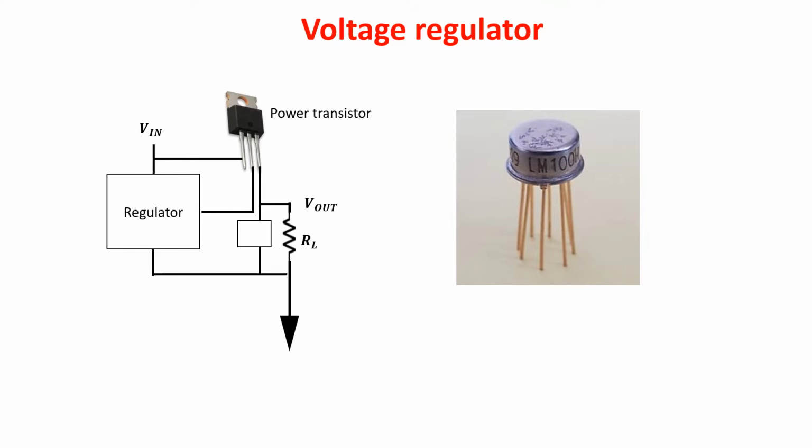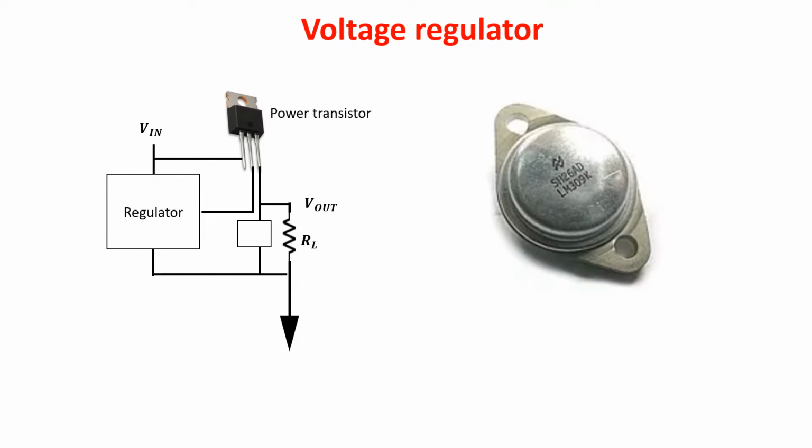It looked like a case closed, but in February of 1970, in another paper, Widlar introduced his LM109, the first high-power monolithic regulator. It had just 3 pins, so it could be inserted in an ordinary transistor power package. It was designed for a logic card, so it provides a fixed 5-volt output and accepts input voltages from 7 volts to 25 volts.